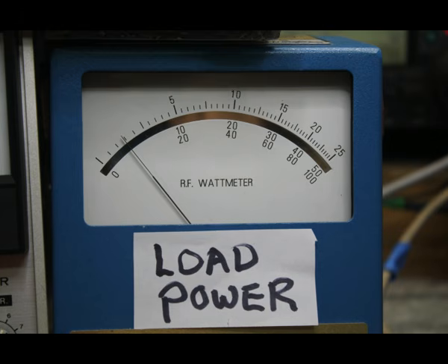Now if we look at the load power being delivered into the 50 ohm dummy load after it goes through the mismatch tuner at the far end of the transmission line, the Heathkit meter told us we should have around 4 watts going into the mismatch tuner, and coming out of the mismatch tuner we have around 3 watts, which seems pretty reasonable to me. So we can see that by subtracting the reflected power from the forward power in the mismatch meter, we came out sort of close to what we really have for the real power.